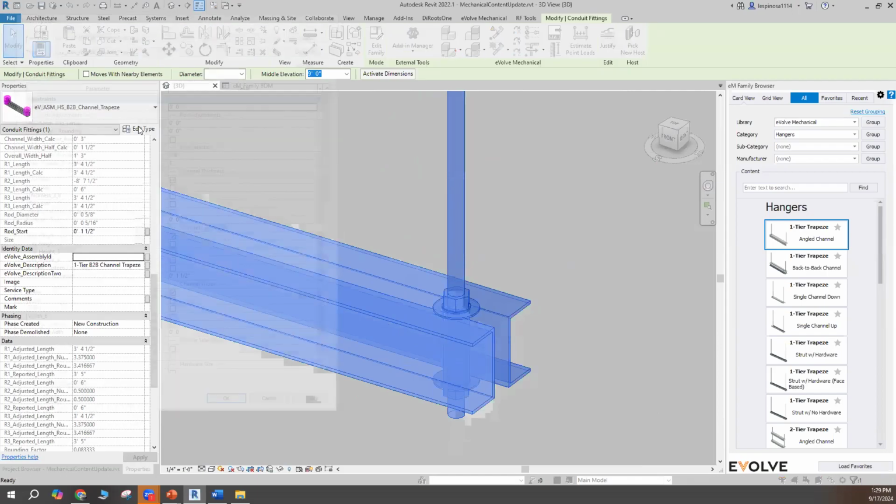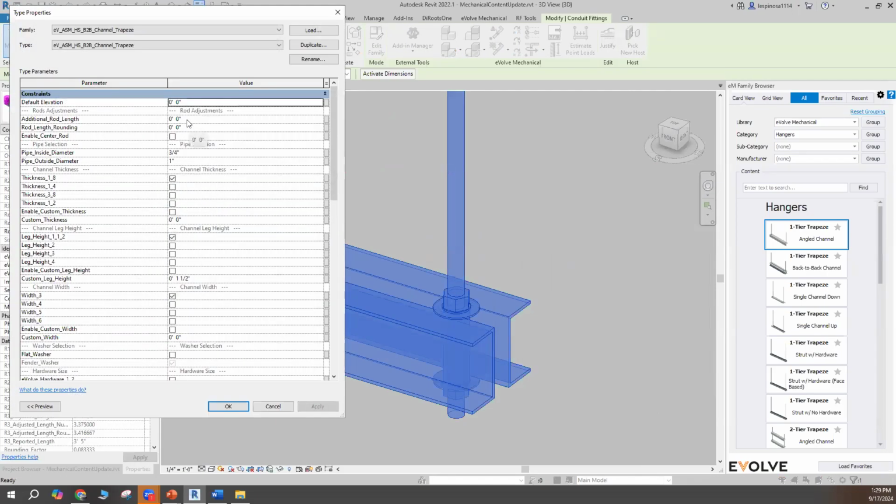Now, rather than try to guess what type of pipe you're using and what OD it is and yada yada, I basically just gave you the option to input whatever pipe you have here. The feedback we received was that what a lot of people are doing here is simply using some scrap pipe they have on the job site, cutting it down to size and welding it to the channel here.